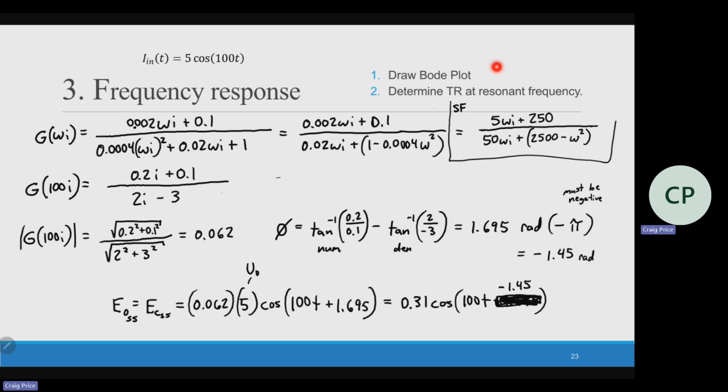So standard form, again, this s squared becomes omega i, all of that squared, so i squared becomes negative. Looks like that. So as we change the frequency, magnitude is going to change. So we can say at a frequency of 100 radians per second, by the way, this is radians per second. If they gave you something in hertz, how do you change hertz to radians per second?